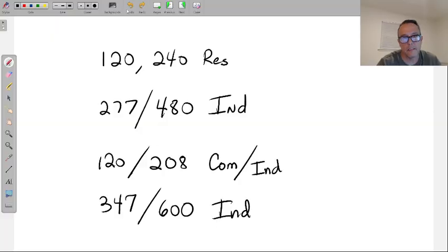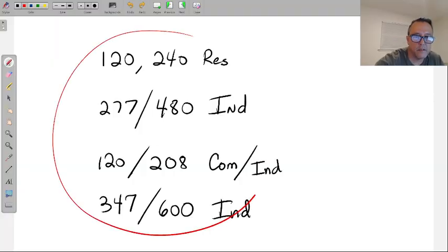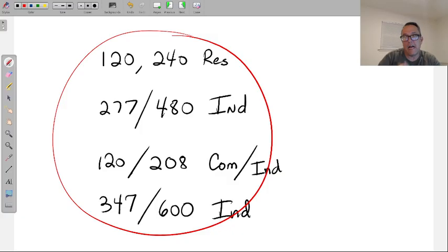All right, this will have some other places where this will show up as well. In worlds like wattage and VA and all this good stuff, especially wattage. Wattage has this little issue as well, because there's wattage estimated that's going to happen when the load is on, and then there's wattage measured, the one that is actually taking place when the thing is energized. And why would the wattage change? Well, because the expected wattage was calculated using a nominal voltage. But when we actually plugged the load into the outlet, well, the outlet didn't have 120 perfectly there. It might have had 122, 123. It could have had 119, 118, 115.